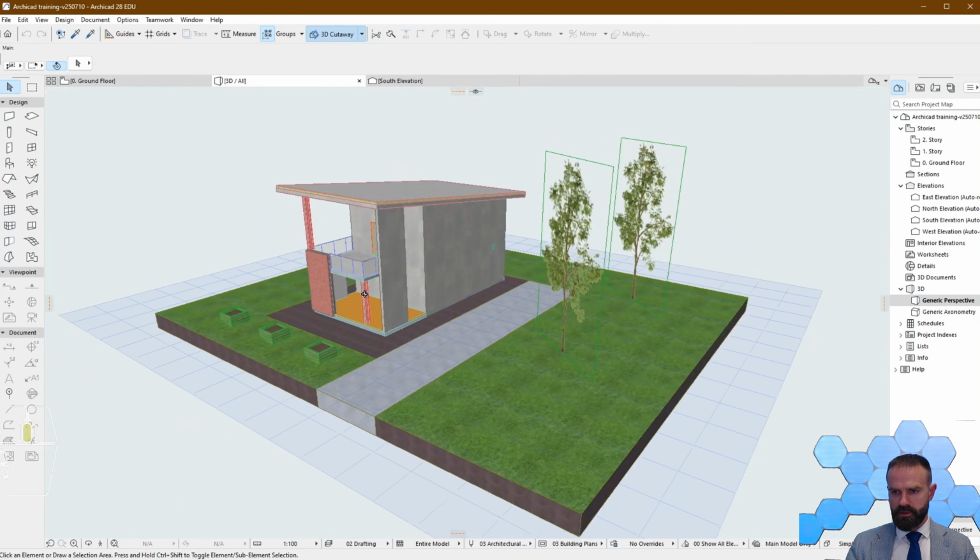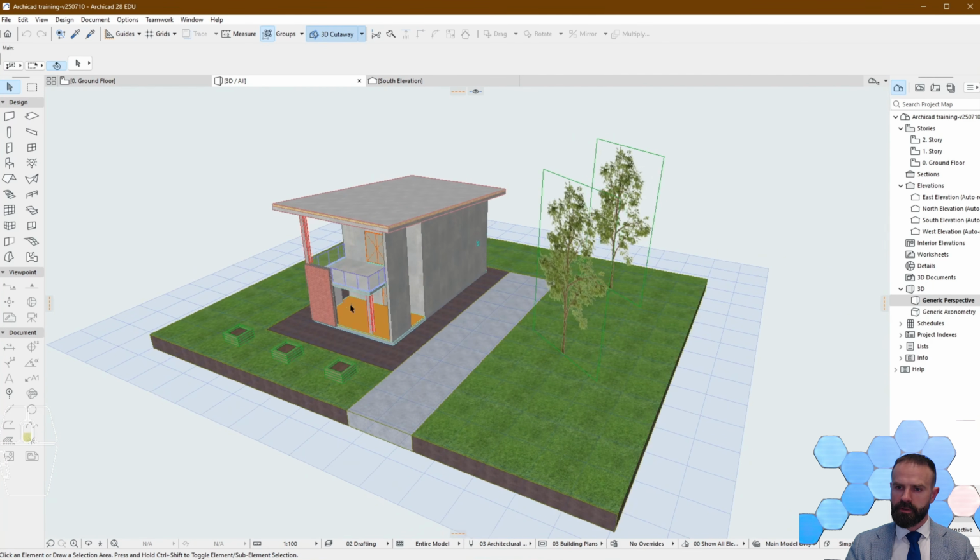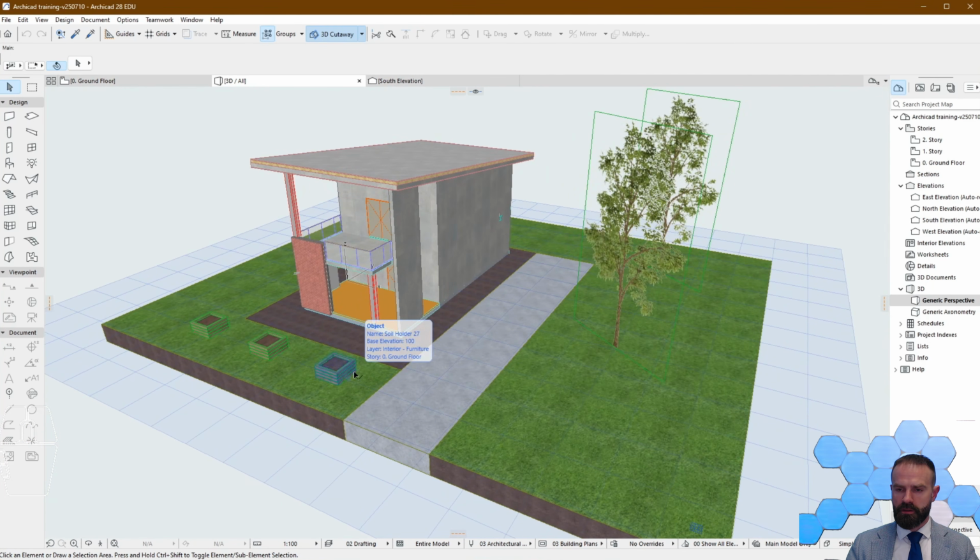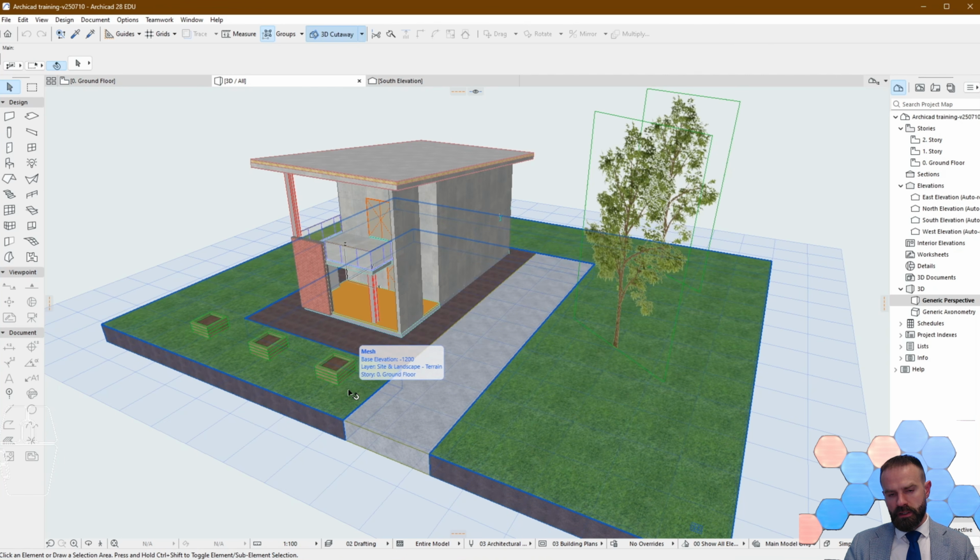Okay, so in this video, let's continue with transformation of ArchiCAD model to Revit editable model. Now in this third part, I will show how to directly convert ArchiCAD model into Revit editable model without implementing Advance Steel. So for this step, we will need to modify the Revit.INI file.